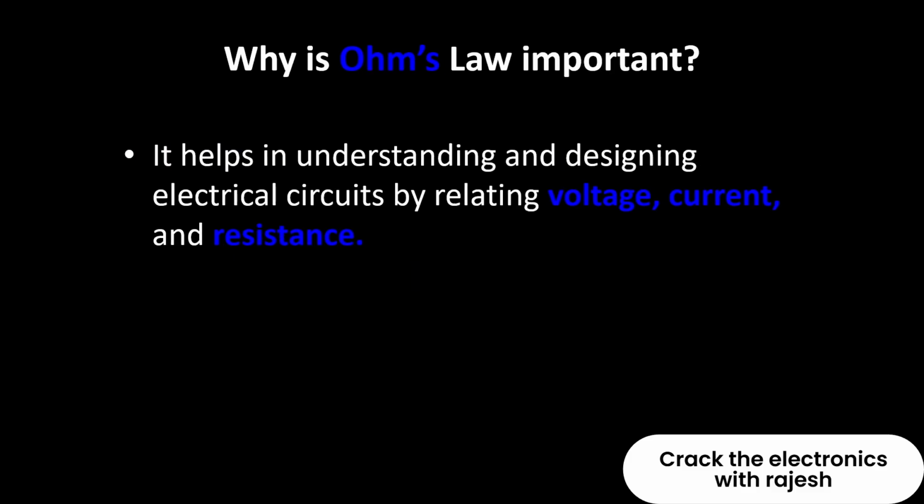Why is Ohm's law important? It is very important. It helps in understanding and designing electrical circuits by relating voltage, current, and resistance. As a design engineer, you should know the formula V equals I into R. It is very helpful if you want to find the voltage drop across connector-to-connector resistance and power planes drawn in PCBs.